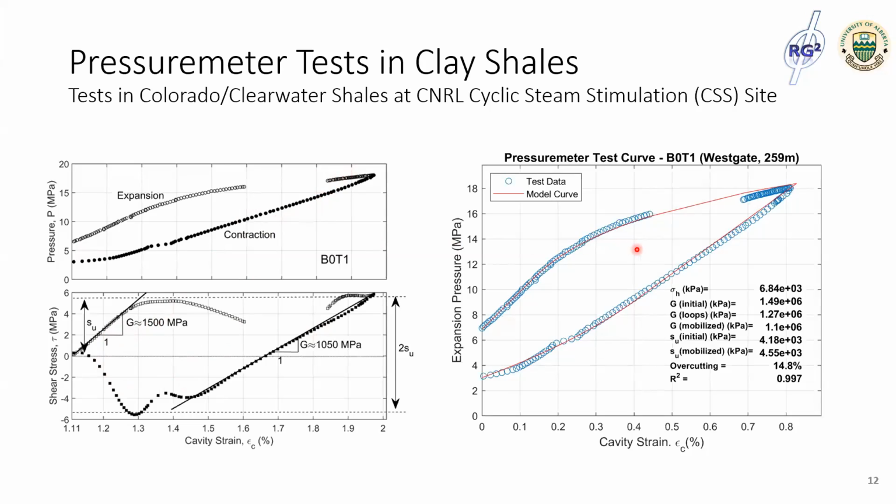The interpretation was also performed by fitting the data with the analytical solutions, as I mentioned before, and a set of parameters including the in-situ horizontal stress, shear modulus, and undrained shear strength can be derived from the best fit of the data.